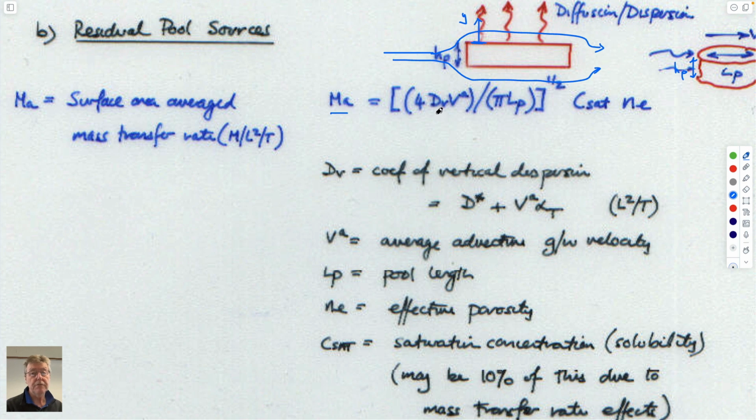It's a function of the dispersion coefficient. Remember, dV is equal to the molecular diffusion coefficient plus alpha times advective velocity, right? This is our longitudinal dispersion coefficient, which is equal to the length of the plume divided by 10, perhaps. We talked about it. And for the reasons that we said, it's not really related to the porous medium, but the scale of the plume.